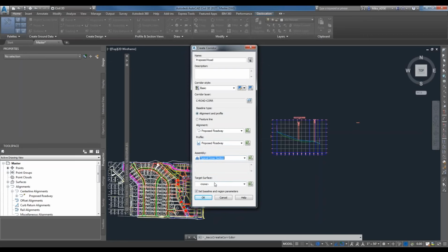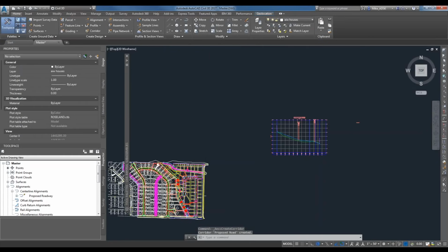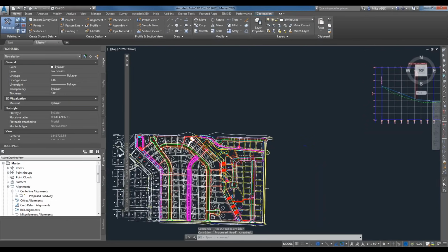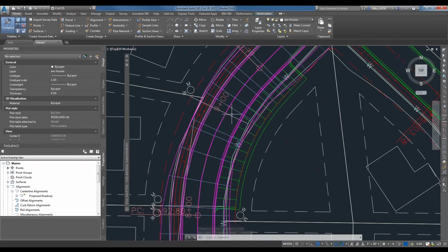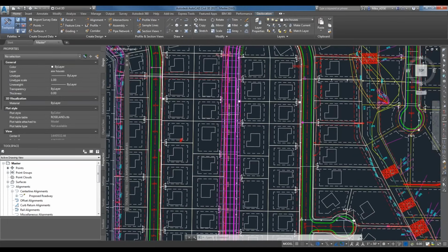Over here, it's going to ask you what surface. So what I had mentioned before about the daylights and how we're actually going to tie this into real life, this is what it's talking about. So I'm going to have those daylights target this existing surface. Not going to select that. Press OK. And now you're going to notice that there's this pretty cool guy right here.